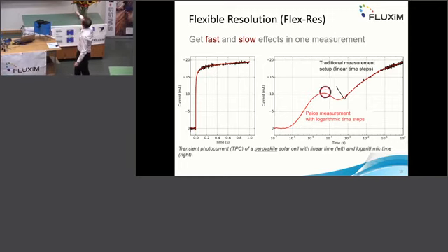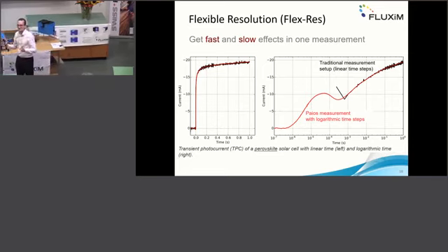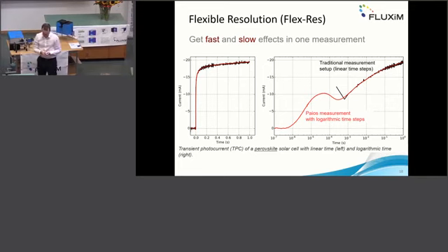That's why you see the red curve is measured by PAIOS, and you see there's a lot of dynamics here, but you still get the slow dynamics too. So you get here up to 7 orders of magnitude in time with one-shot measurement. Because in perovskite, you may think you could also measure it several times and then stick it together, but the experience is that the perovskite solar cells don't like that very much because they change a bit in the meantime, and then it doesn't match. So this is especially for perovskite solar cells or for other devices with broad dynamic ranges. This is very, very interesting.